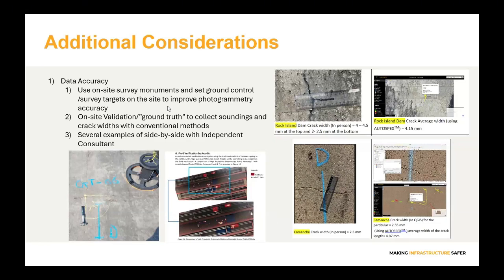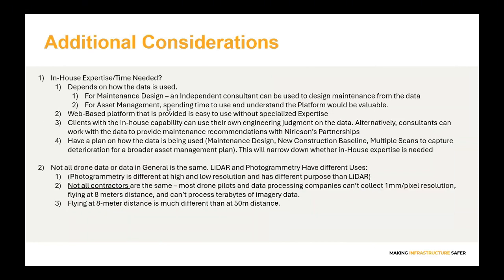It's also really important, if you are going to implement drones for your condition assessment program, to make sure they collect ground truth data. For us, that means going out, setting crack gauges with our clients, and having independent verification as well. In our case, for our acoustic sounding hammer, it means being able to tap the structure with the drone and also measure it with the conventional sounding systems.